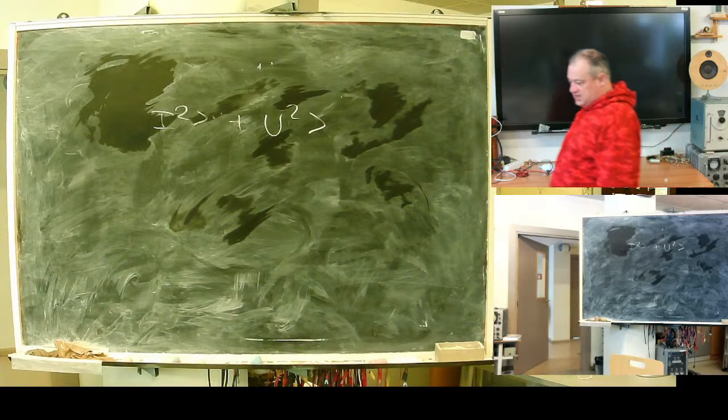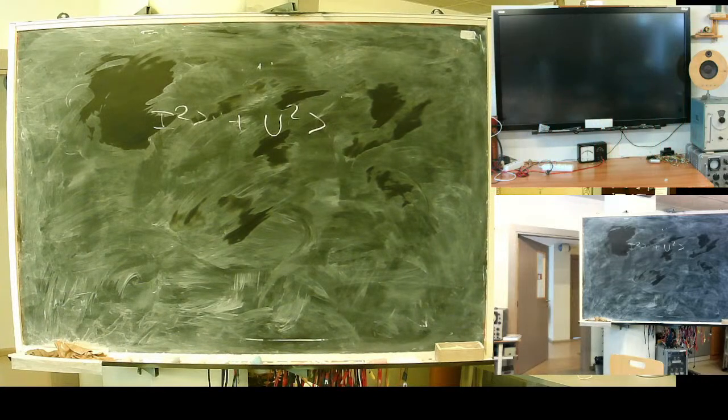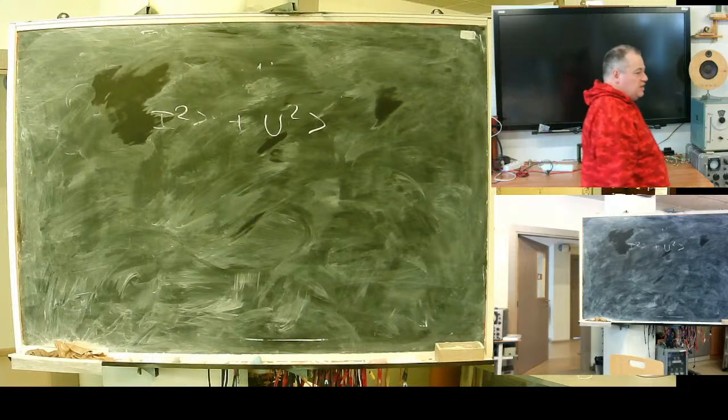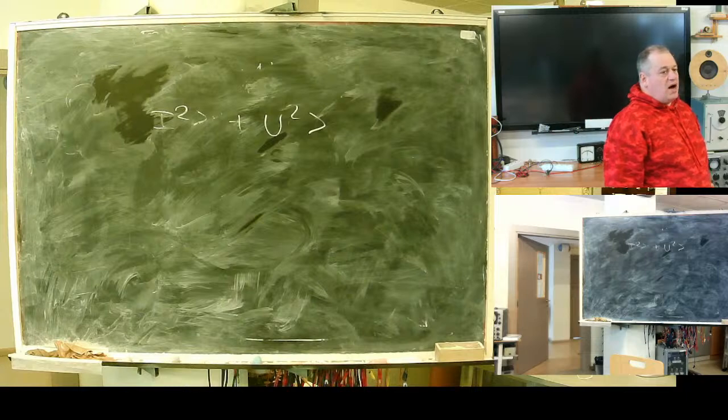Negative sequence presence was used as a criterion to unblock distance protection. Distance protection was blocked until this criterion was met. It is not reliable.